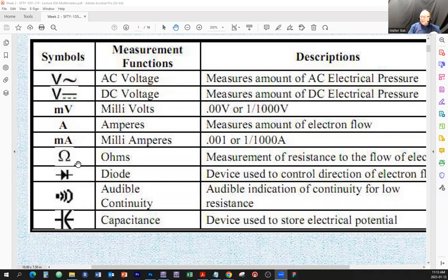With capacitors, the dominant quantity is capacitive reactance, and with coils, it is inductive reactance. But if you combine its resistance and its reactance in one device, in combination it is called impedance.